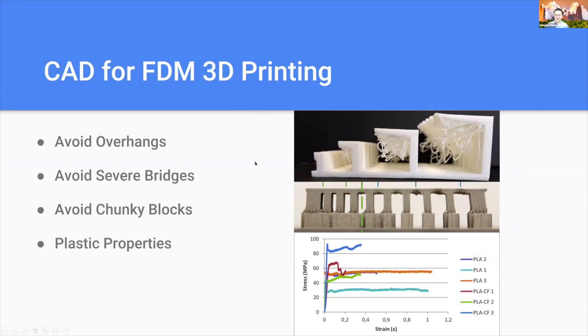So moving on, I want to talk a little bit about how you can optimize your 3D designs for 3D printing in particular. Right. So on the top image on the right, you see what we call an overhang. And moving from the left to the right, the overhang gets bigger and bigger. And as you can see, when the overhang is larger, the print quality decreases significantly. In fact, on the very right, the print that you have is essentially not usable, right? So you want to avoid large overhangs like these for fused deposition modeling 3D printers, right? What happens here is